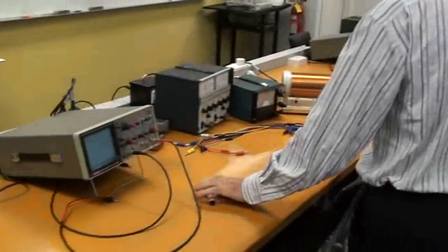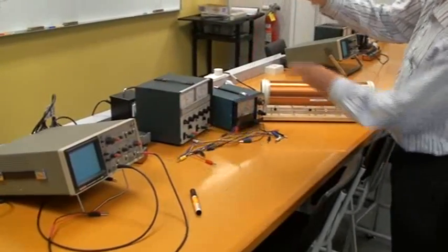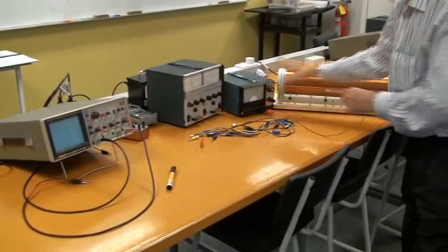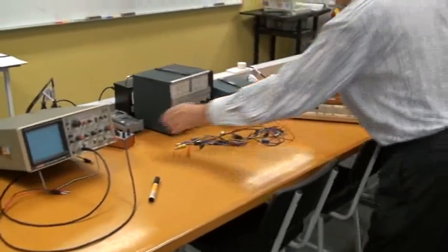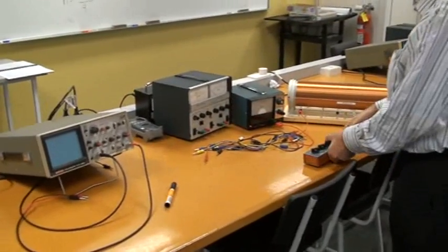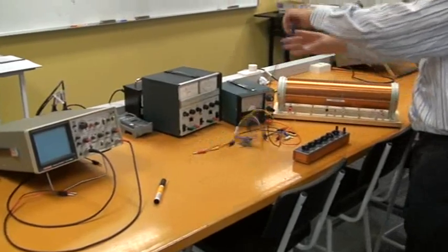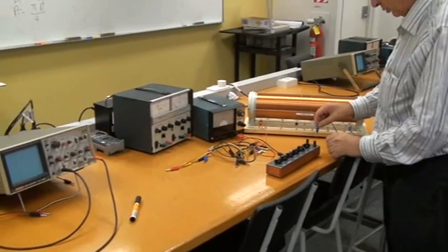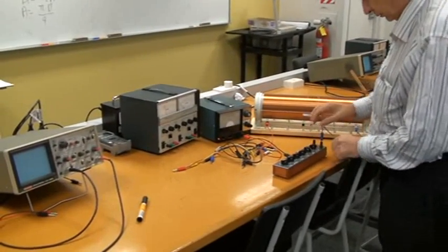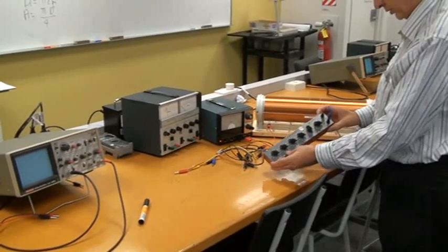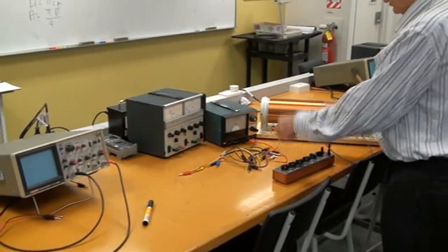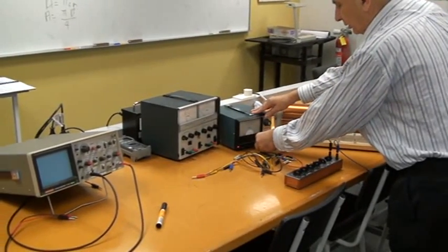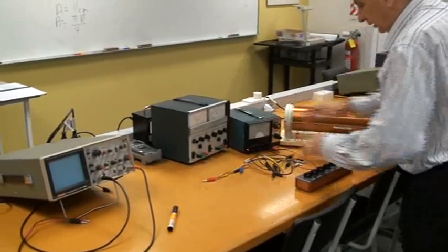Now to do this, we're going to take a supply from the signal generator and pass it into coil number 1, and then the current will flow out from coil number 1 into a resistance, and the resistance we're going to use is 200. So the resistance box is set to 200. And finally, we go back to the earth on the signal generator. So do you see, we set up a series circuit with R and L in series.